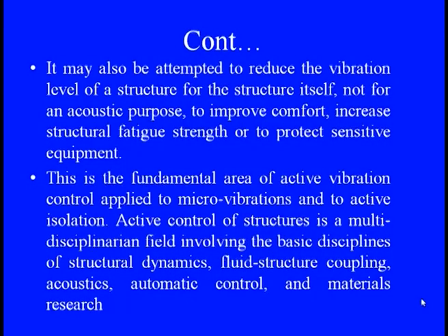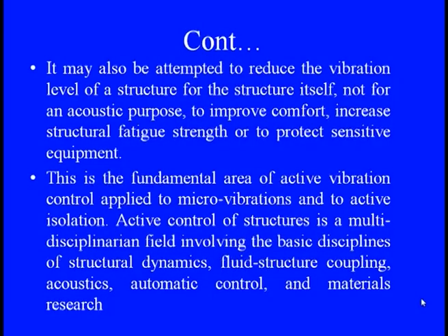So, we can say that this can even be attempted to reduce the vibration level of the structure itself, not only for the acoustic purpose, and through that we can improve the comfort, we can increase the structural fatigue, or cyclic loading strength, or even sometimes we can protect the sensitive equipment by suppressing the vibration. So, this is the fundamental area of active vibration control, which can be applied to even the micro vibrations and to active isolations as well.